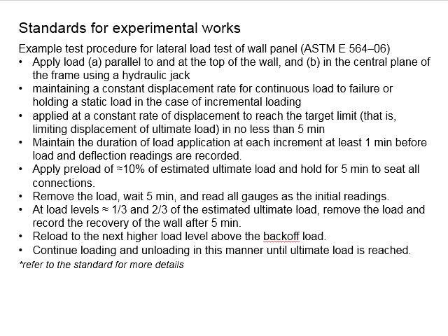The first cycle will be from 0 to 1/3 of the estimated ultimate load, and then going back to 0. This leads to the second cycle, which is from 0 to 2/3 of the estimated ultimate load, and then going back to 0 again. The entire response of the specimen shall be recorded and monitored throughout the testing. Next, you reload again to the next higher load level until the ultimate load is reached.